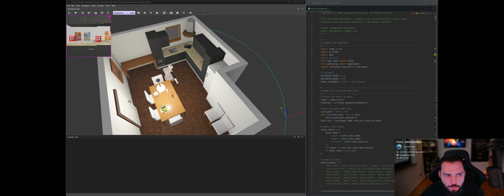So that would show all the joints of the entire robot, all the joints that you would need in the arm, their minimum and maximum rotational positions, and also the height of things. So a big thing, you have to calculate where certain things are on the robot's body in order to use that calculation or offset. For example, the camera in the robot's head, you would have to figure out the torso lift position, as well as where the camera is located and the height of the robot in its head in order to correctly calculate the location and the height, the Z parameter of any objects that you're recognizing.